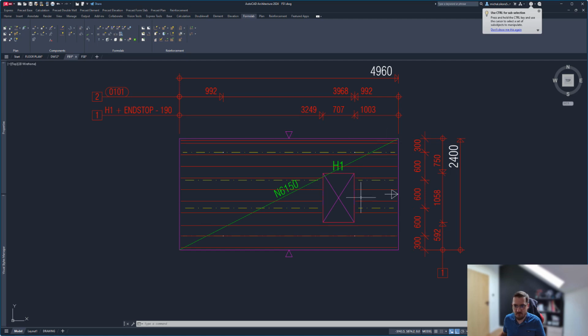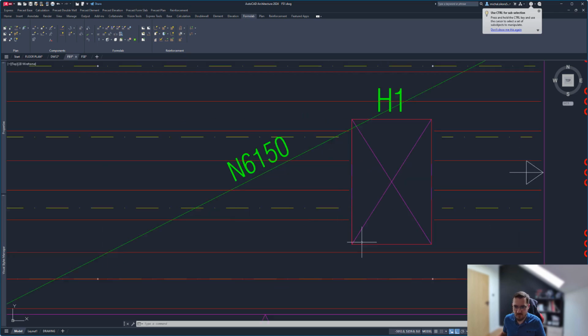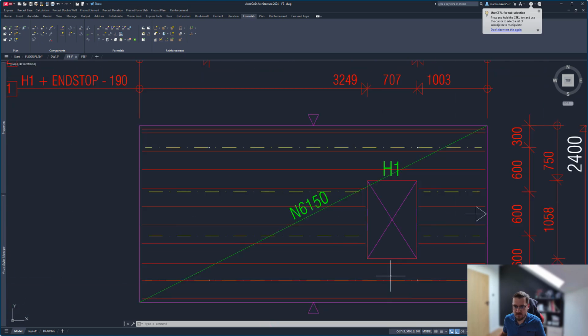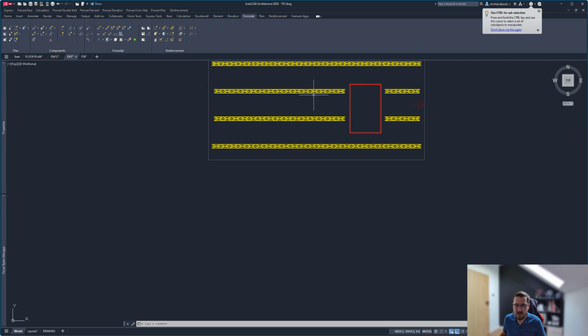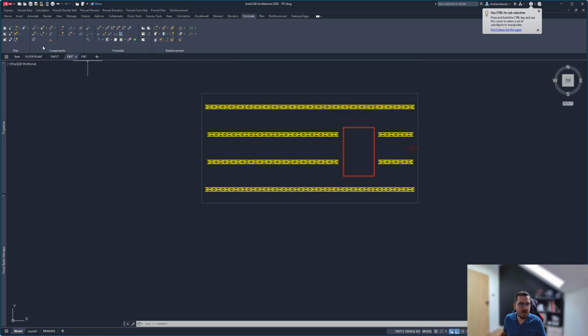So you have the girders here, basically some additional reinforcement, red reinforcement, yellow girders. Girders are cut here, maybe warrants moving reinforcement a bit, and we have those girders as well. Now, if need be, of course, we can, for example, draw a lattice girder, and we can specify the type of lattice girder that is. Let's maybe do this one, and we can specify that from here to here.